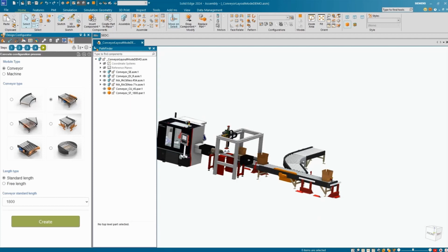It didn't really show it here as much, but you can actually bring in a sub-assembly that has a configuration on it, and then that sub-assembly's configuration will start. And so you can have various looping and sub-configurations in a row to build some extremely complex and large models if necessary.